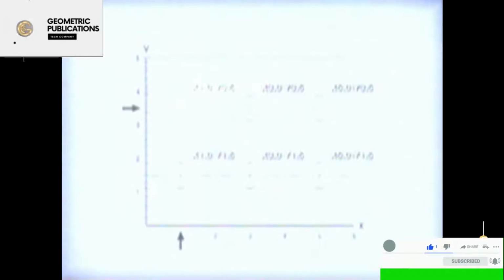These coordinates indicate the position of the cutting tool center and are collectively called the tool path. The location where the rectangular coordinate baselines intersect is called program 0, which is a common or reference point from which all coordinates are derived.